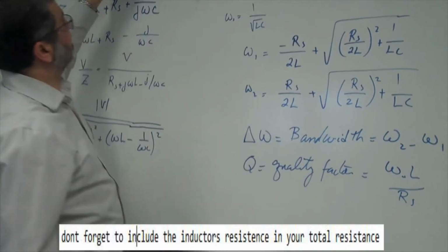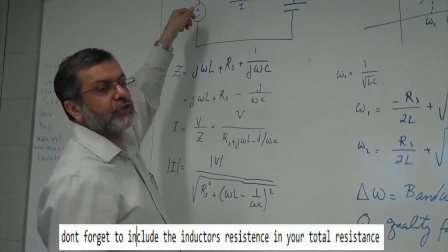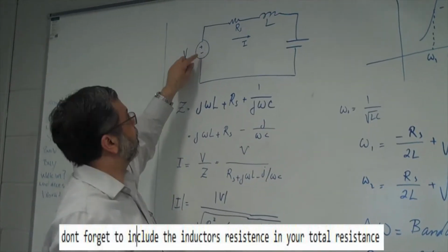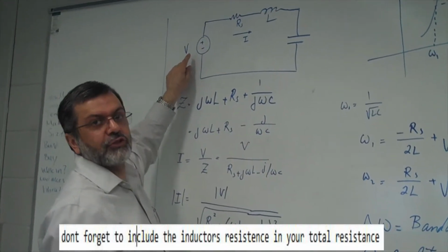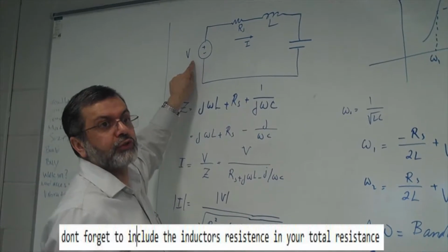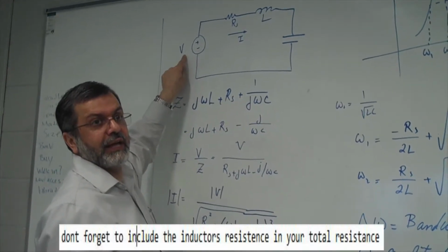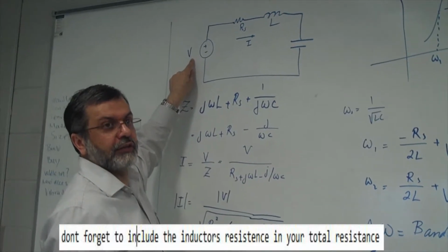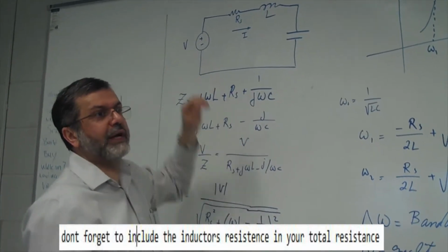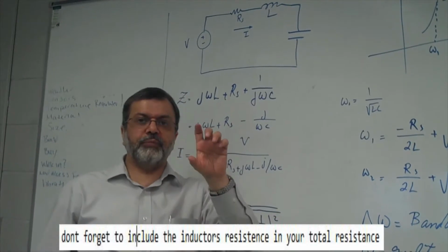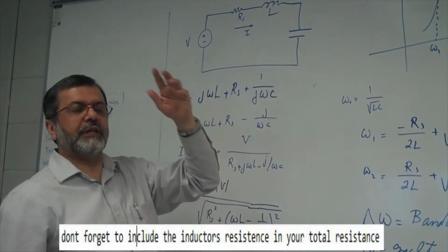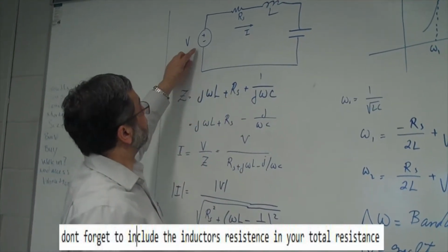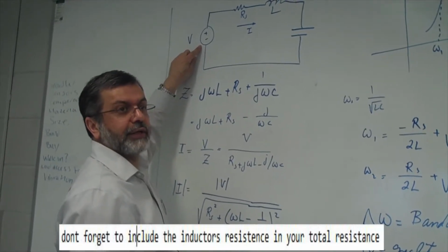We're going to set up this circuit, and we're going to change this. I'll probably ask you to use 1 volt RMS. That's AC in your scope. This is not a DC. It's AC in the scope. So 1 volt RMS, that means, to get the peak to peak value, you multiply that by square root of 2. So 1 volt RMS or something like that.